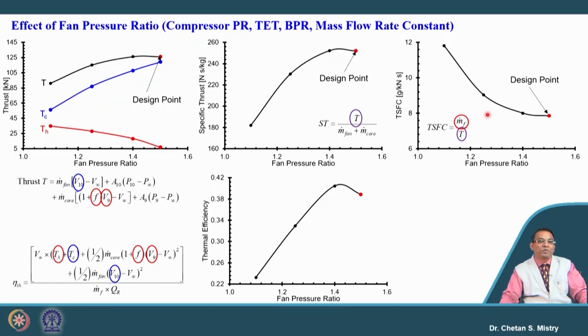Similarly, suppose this is representing our thermal efficiency, and it says our thermal efficiency is in the range of 36%. So, what is the meaning of that? All the information we have taken is actual engine information, and now you can realize that the analysis we have done and the numbers we have selected are optimized parameters. They must have been optimized for the thrust specific fuel consumption to be lowest, and that is the reason why this fan pressure ratio is an optimized number for our calculation.